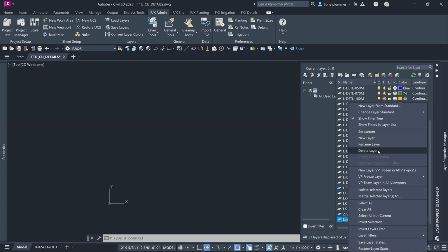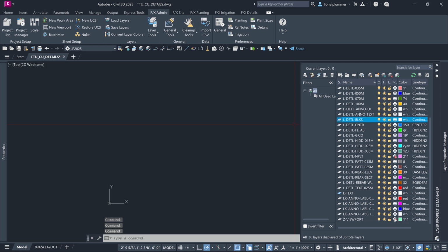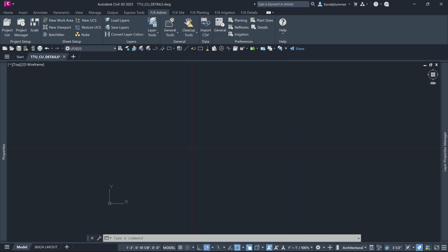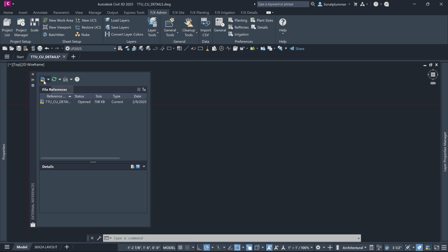Okay, so let's delete that layer that we just made. You didn't have to make it, but this is not a good layer to start anything with. Okay, let's just use this guy, plain Jane. Okay, and now Alt N is new layer, and you're going to call this X, and we're just going to call this reference. Now double click on here to make that active. Let's open up our XREF. All right, and we are going to XREF in an image.